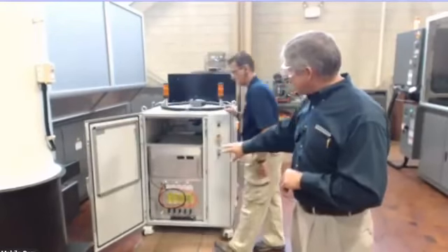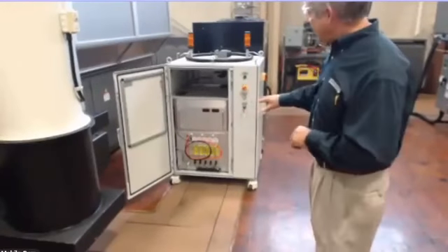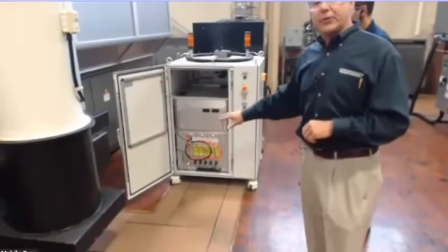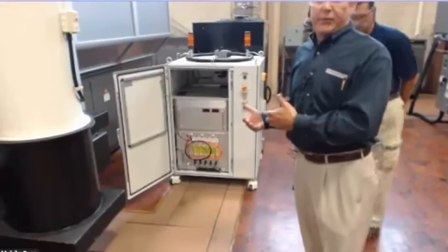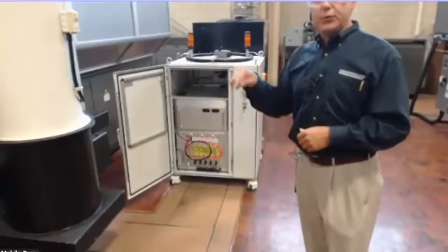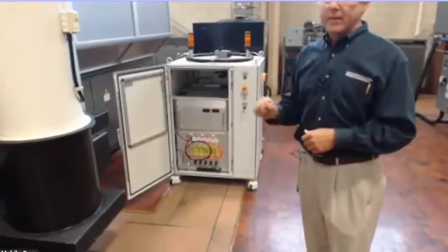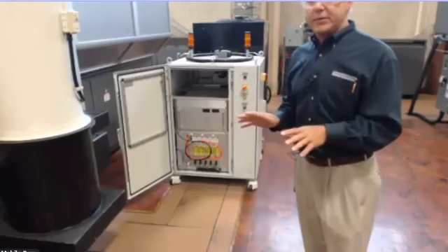resonator. So here, instead of opening up the cabinet and seeing glass tubes, what you see here is completely solid-state modules. There's multiple modules. The laser beams that are created in those individual modules are combined and then sent through the fiber optic beam delivery over to the cutting head. So that is another difference on these two.